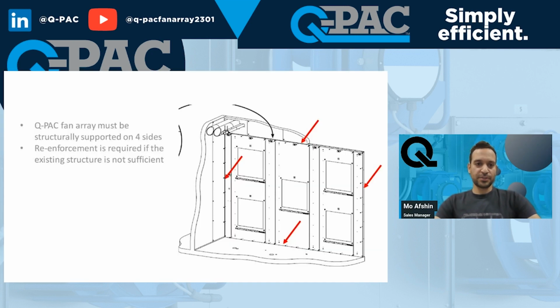And I have structural support for our fan arrays. This is a question that sometimes comes up. A lot of our systems may go into an air handler that is already designed to have a fan array in it. But a lot of the time that's not the case. You're working on a retrofit system, and you're replacing an existing fan that is a completely different fan. So the support may be different. It may be a built-up system. It may be just an air tunnel where you're adding a new fan array. So the support may not be there for the fan array.